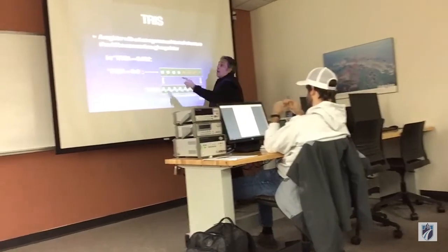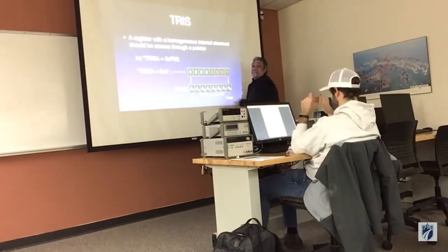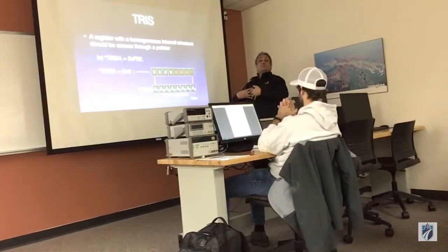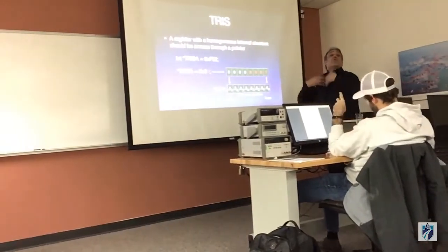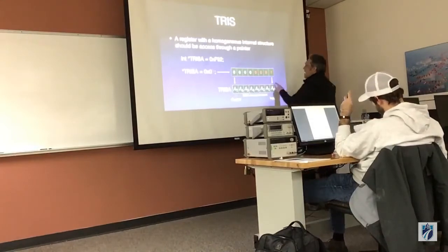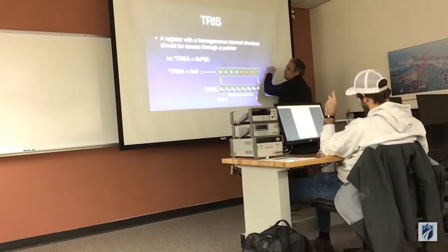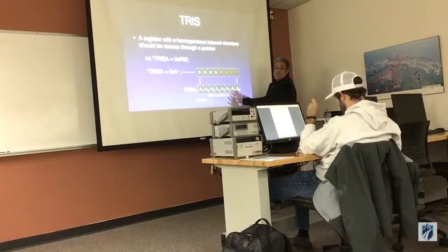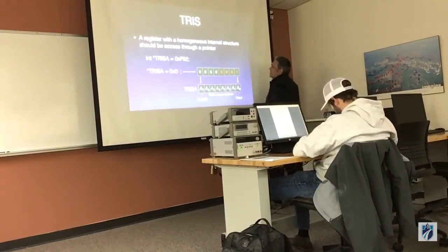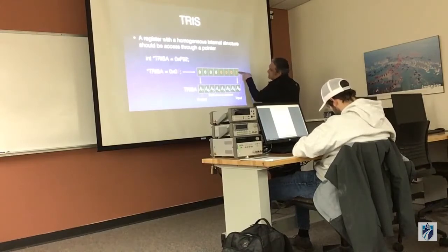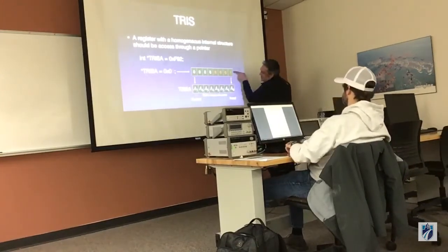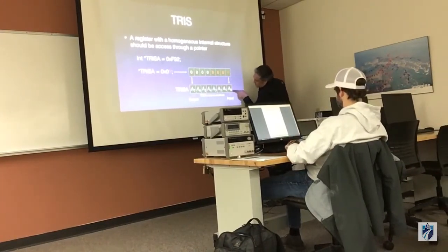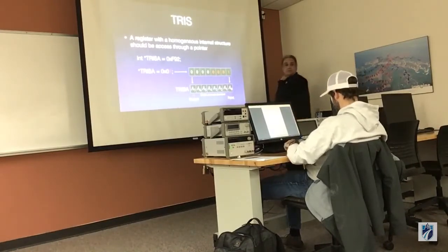Now, once the software does that, the circuit is going to behave according to your command, right? And that's what these arrows are telling you. So this is what the software does. This down here is the behavior of your circuit. So here's what happens. When the 1 is deposited inside of that tri-state device, the circuit corresponding to pin 2 gets configured as an input.